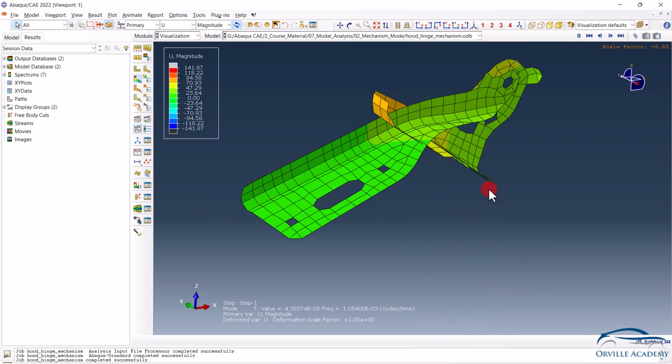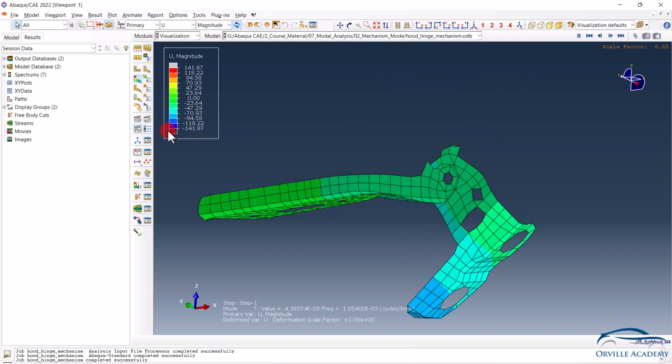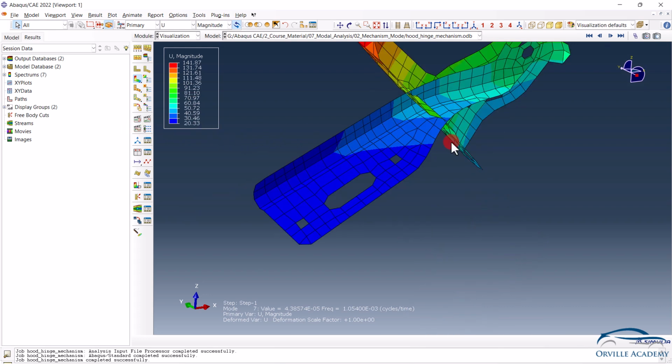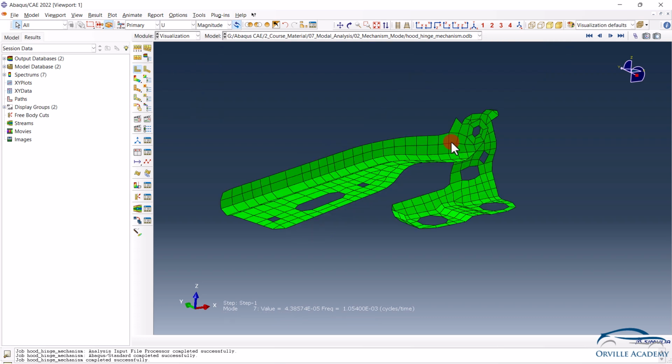Now here, in order to get a better understanding, one thing that we can do is to fix the body side hinge itself. One might ask a question, why the body side hinges? Because typically there are a lot of load cases which will get performed on the hood alone. Since this particular body side hinge will get mounted on the BIW, which is much stiffer, it makes sense to constrain these two locations.